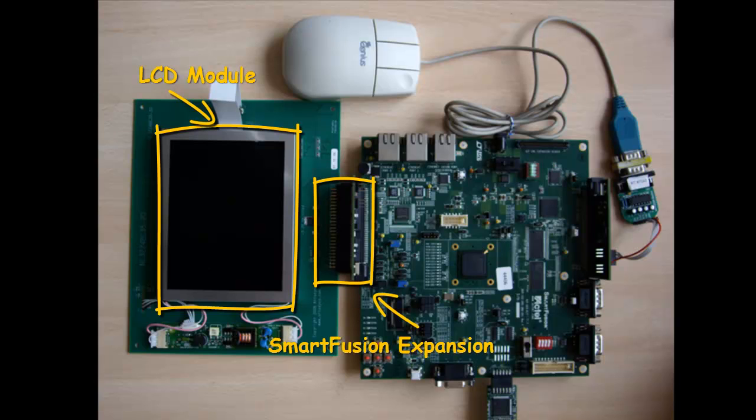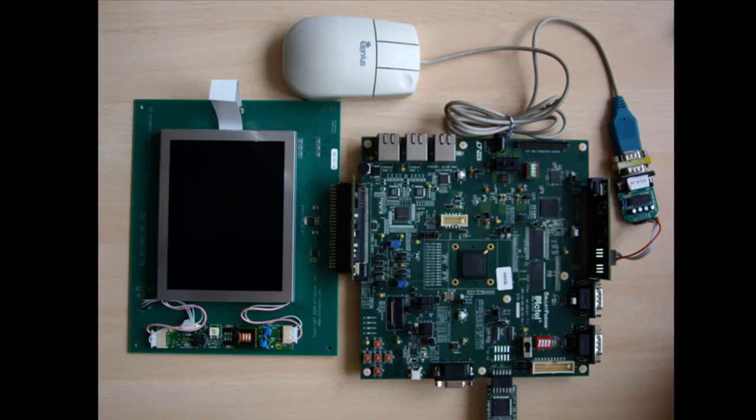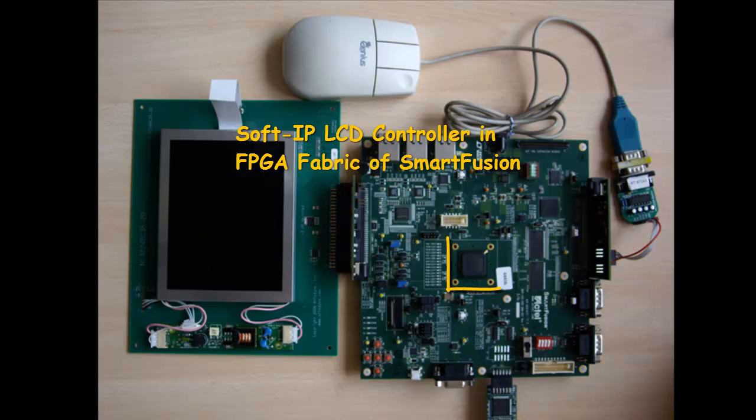The LCD module has a 240 by 320 resolution supporting a digital RGB interface with 16 or more colors per pixel. The FPGA fabric of the SmartFusion is used to implement a soft IP LCD TFT controller compatible with the interface of the LCD module. The IP includes a dedicated DMA block responsible for constantly fetching pixels from the video frame buffer that resides in the external SRAM memory and placing them into a FIFO buffer residing in the FPGA fabric